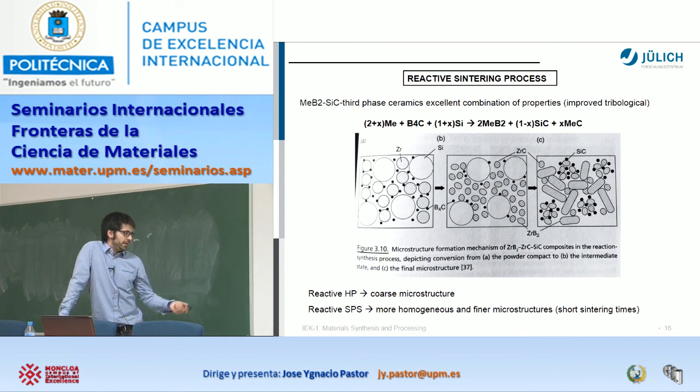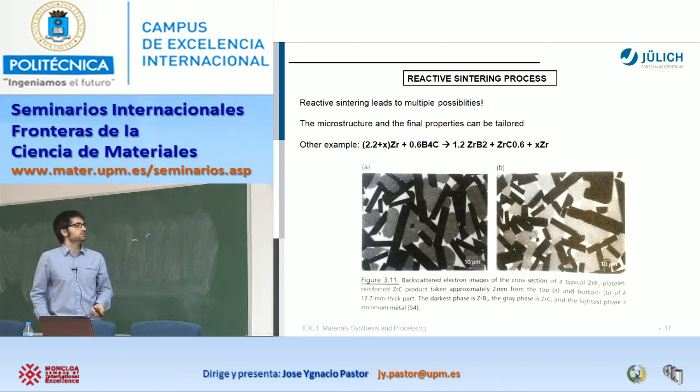Okay, and again, if you do hot press or reactive hot press, you obtain a coarse microstructure, of course. If you do it in SPS, it will be a finer microstructure, again because of the short sintering times. And here, okay, perfect.